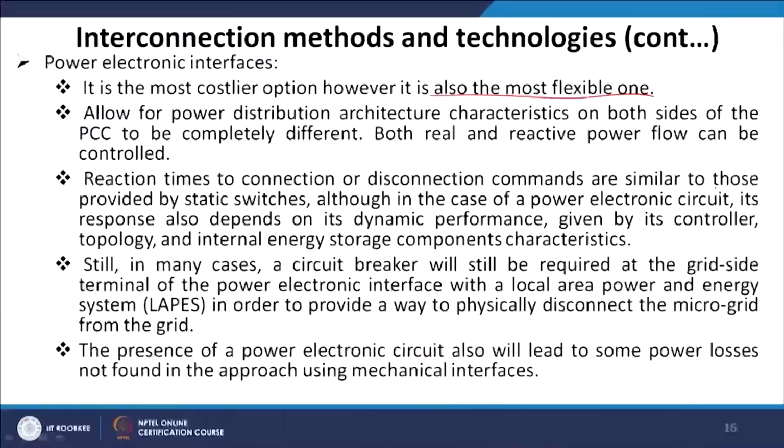Reaction times of the connection and disconnection commands are similar to those provided by the static switch, because it also uses IGBTs only. Although in this case it is power electronics, its response depends on the dynamic performance given its controller topology and the internal energy storage component and characteristics. Still, in many cases the circuit breaker will still be required at the grid side, because you have to deal with arc quenching and leakage current; those issues have to be tackled.